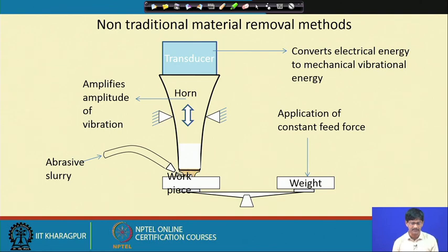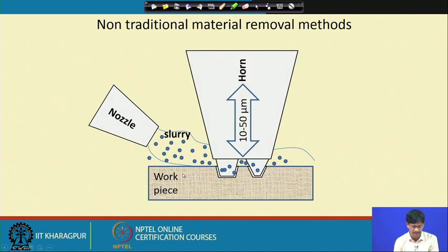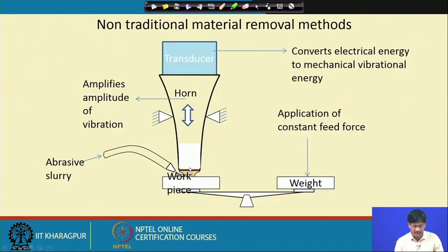The ultrasonic machining method, first of all, has a transducer where electrical energy is converted to mechanical vibrations. These vibrations have their amplitude multiplied by a device called a horn, by its very shape. When the horn vibrates, it creates an amplitude of around 25 microns at its end, where we fit a tool of a definite profile against the workpiece.